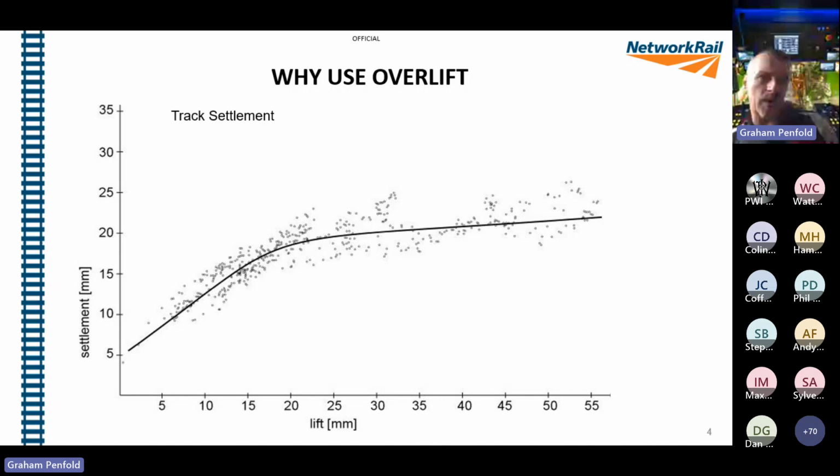And also when we lift track, particularly with tamping, the ballast isn't quite consolidated again, so we'll have points of ballast on the edges of others, and under the dynamic loading of trains, these will break, causing ballast damage, and hence it will settle a bit further down than what we lifted it. So when we limit lifts to 10 mil, close tolerance lifts and stuff like that, sometimes I've got my head in my hands thinking, what's the point of sending out a machine?